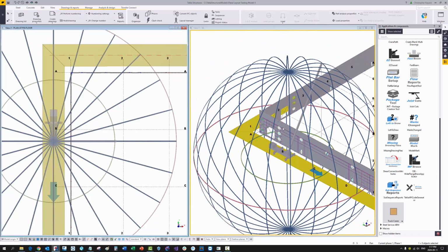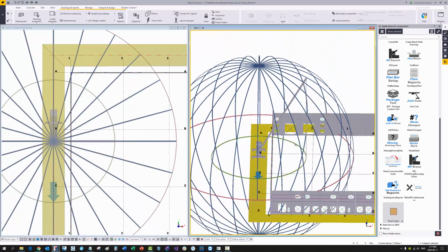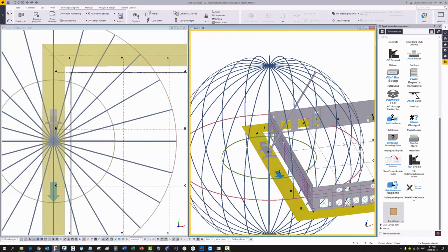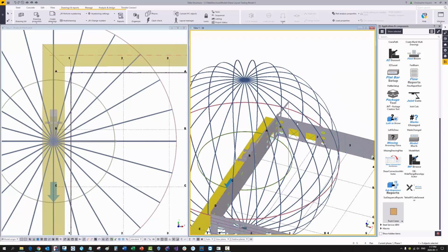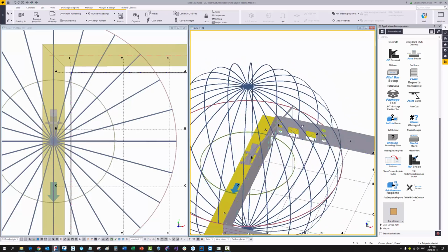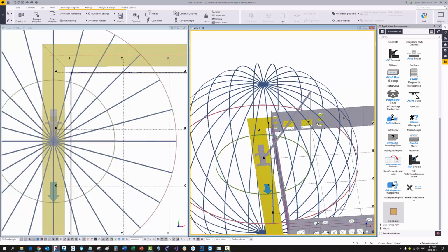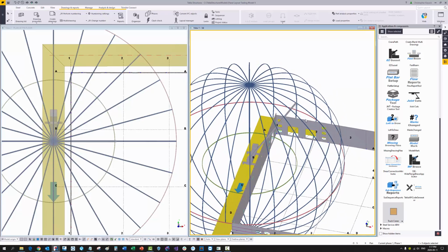Now, I've got the boom here set at 60 degrees, and then you can also see the maximum radius for this particular boom length as I change the boom angle. And then we can just get a feel for actually where our crane can move and where it can reach, and then we compare that against our crane capacity charts and the weights of the panels.